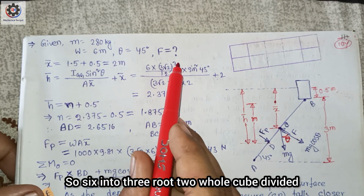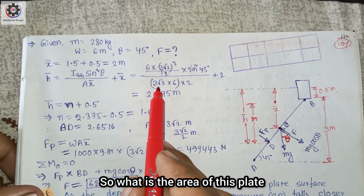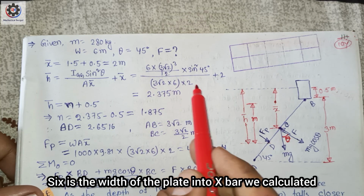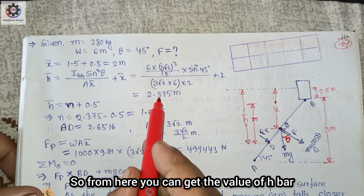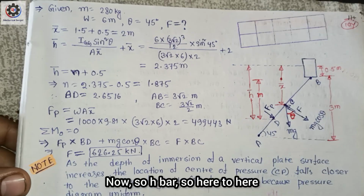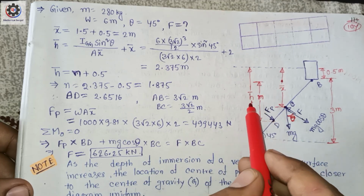So 6 into 3 root 2 whole cube divided by 12 into sine square 45 degree divided by, so what is the area of this plate? That is 3 root 2 into 6, the width of the plate, into x bar we calculated, that is 2, plus 2. So from here you can get the value of h bar, that is 2.375 meter. Now this is the center of pressure. So here to here, this is the distance h bar.